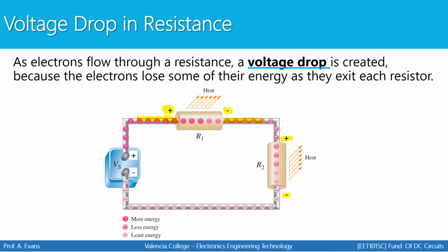You're always going to have to remember polarity. Polarity will be a huge factor in this course. So as you're labeling your voltage drops, keep in mind the positive end of your voltage drop is where current enters. The negative end of your voltage drop is where current exits when it comes to labeling these voltage drops across resistors in a circuit similar to this one.